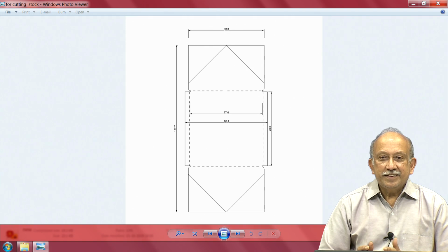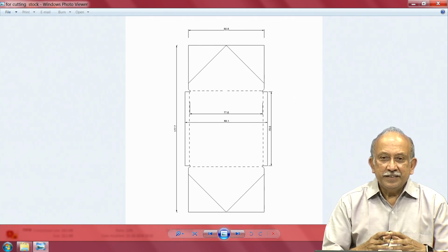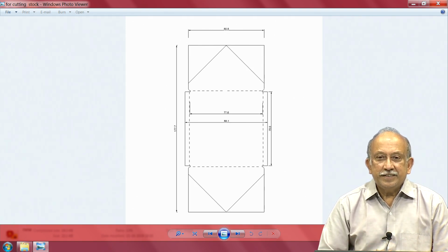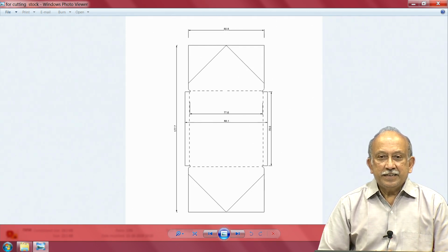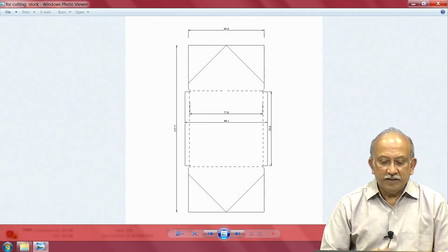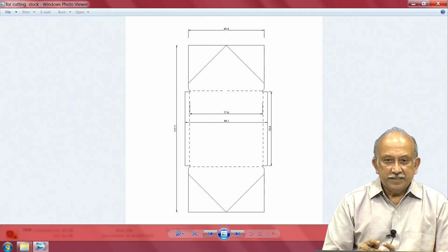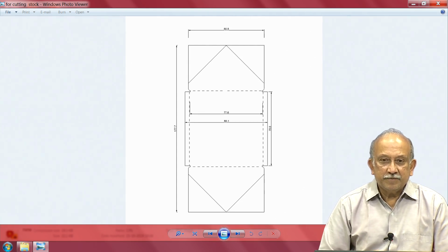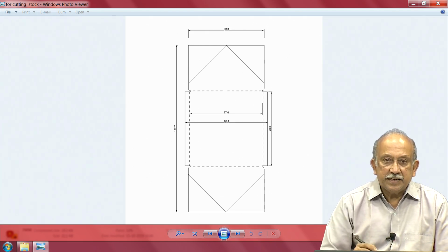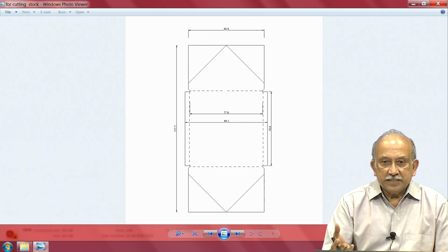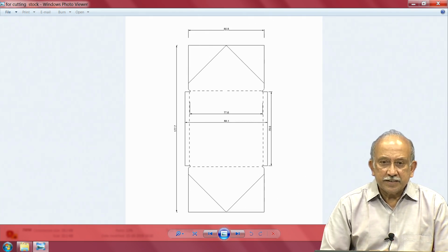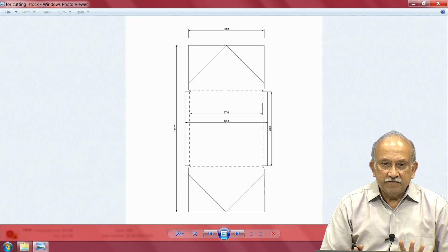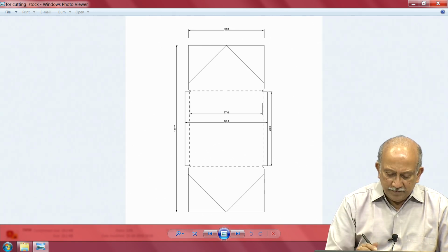and there is no necessity of using very accurate marking and measurement metrology items. All we need is something which is approximately okay, up to the order of say plus or minus 0.1 or 0.2, and is consistent. If I maintain the direction of printing, sometimes it is around 0.1 millimeters larger, then I can just go ahead and live with it. Yes, this is a printout which is made